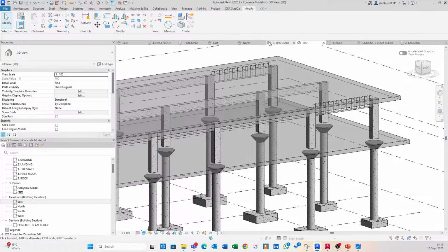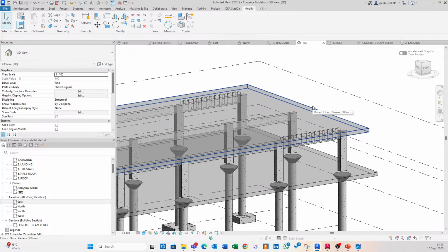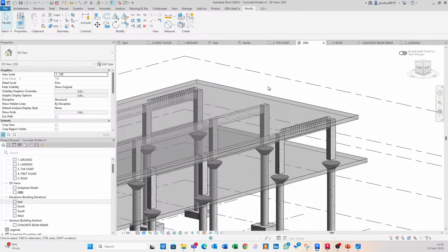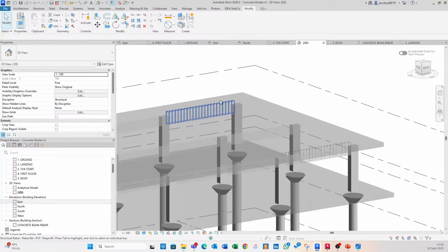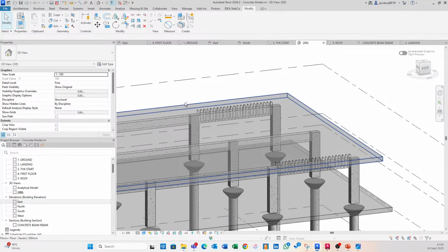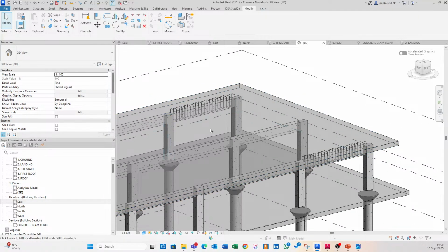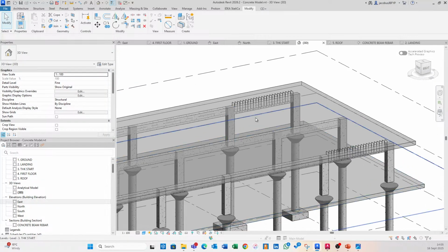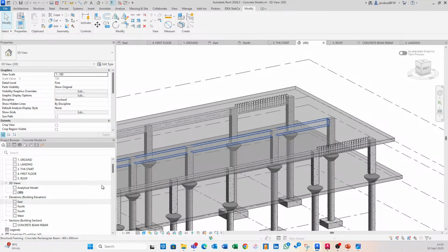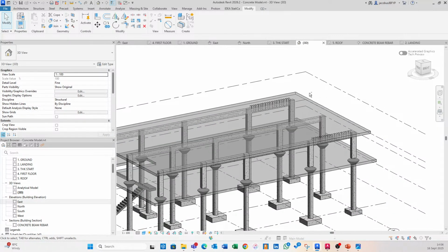You can see that I've got quite a lot of views open here. The reason for that is that your rebar detailing in Revit really comes down to the creation of different views using sections, etc. That is really how you get into the nitty-gritty. Don't try to do rebar detailing in 3D. I don't even think the program necessarily allows that. It could have changed recently, or it can change in the future, but you want to create views. So you'll have a lot of different views, and then when you get to the end of everything you might delete those views, or you just might group them differently, whatever it might be. Views really are the secret.